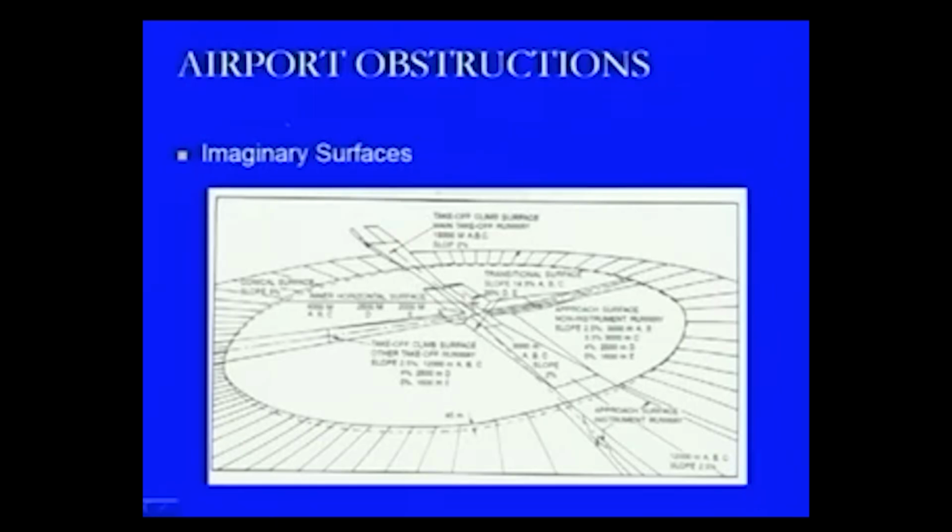So, this is provided like this, then there are the transition areas being provided at these locations. And this is 3000 meters for A, B and C, slope is 2%, then this is a 45 meter variation in this level. Then slowly we are moving further. We have 12,000 meters for A, B and C with a slope of 2.5%. That is how it is moving further.